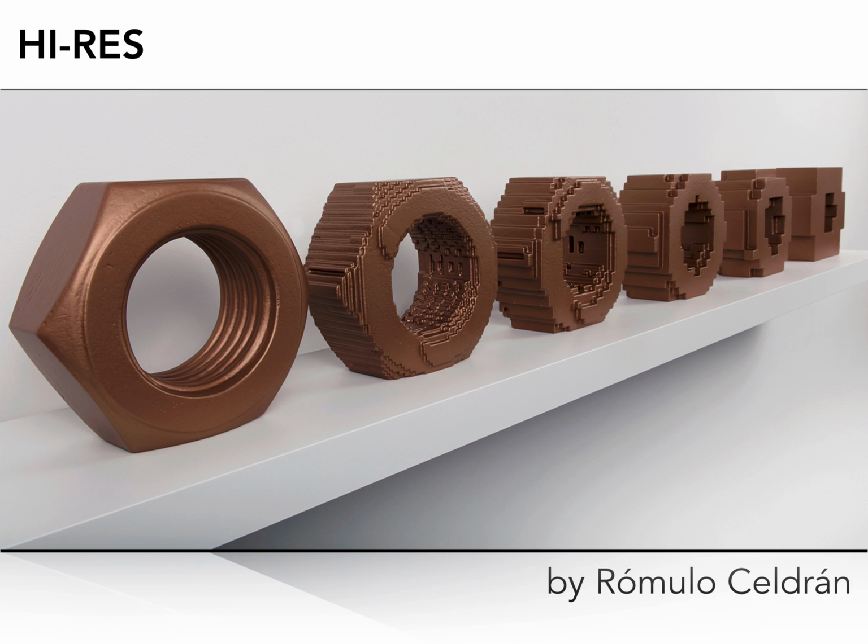This is called H refinement, and it's one way to improve on your approximation. The other way is just to keep your original mesh and then increase the polynomial order of your approximation, and that's called the P version of the finite element method, and we will also be looking at that in this class, okay?